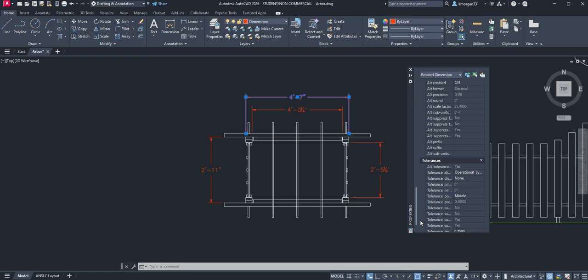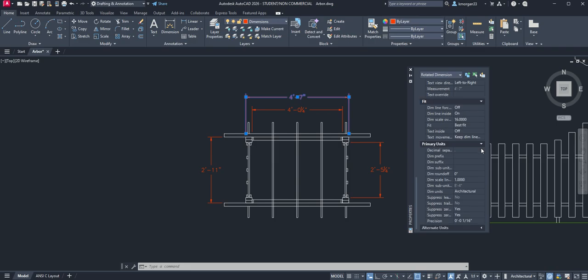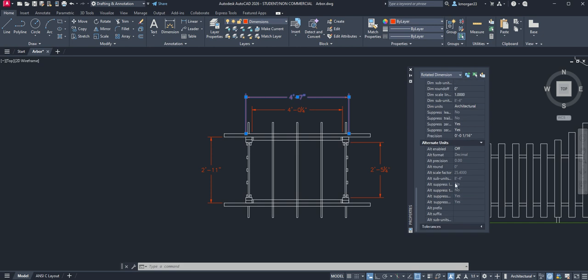Okay, so here you have tolerances. See, there's a little drop down. You can close, okay, like that. Of course, you can also go down, yeah, this way. You can open it, so it will open. So that's your collapse and expand little button right there, yeah, to open each of the tabs in this properties window.